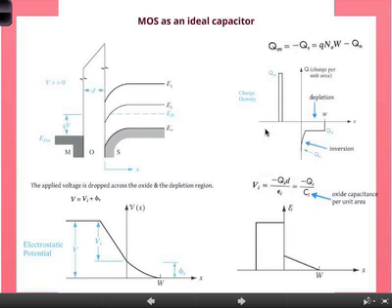Now, if you look at the charge density, in the ideal case, there are no charges within the insulator. Oxide cannot contain any charges, ideal oxide. At the interface here in the metal, you have some charge accumulation, positive charges accumulate at the interface of the metal. And on the other side, in the semiconductor, of course, we have an inversion channel.